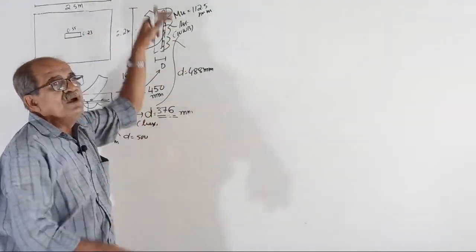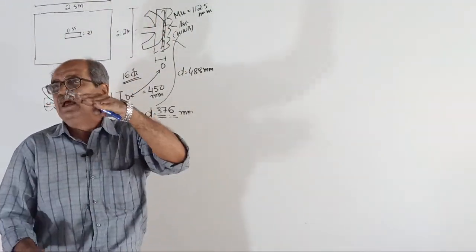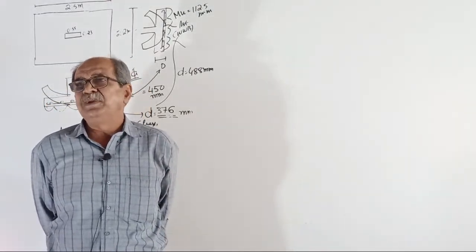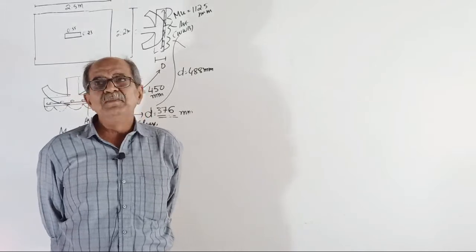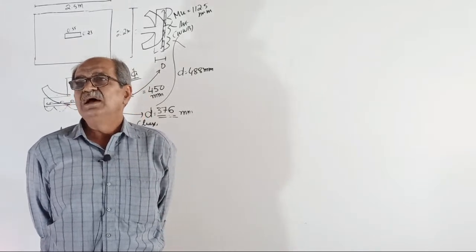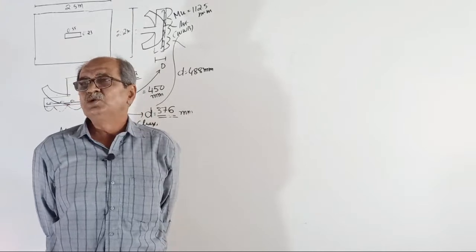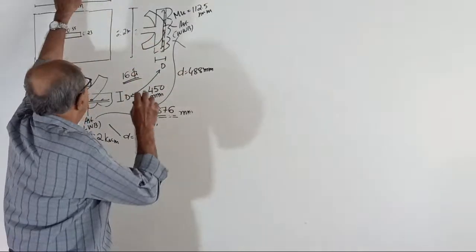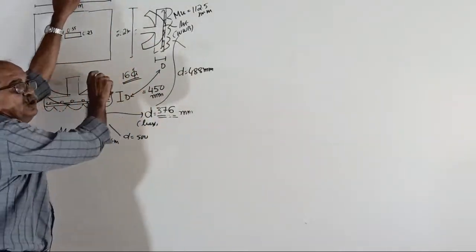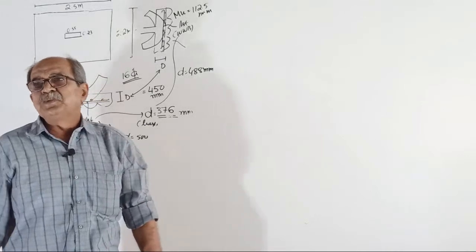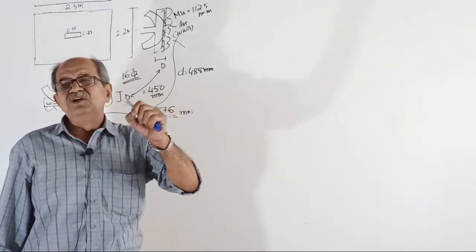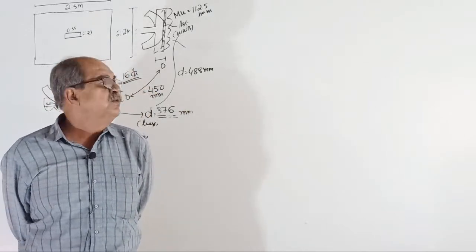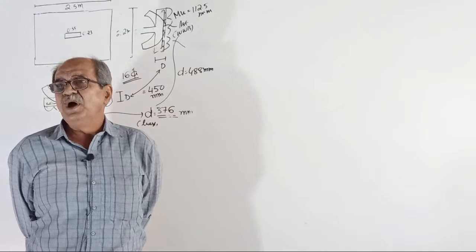Around 450 came, so you took overall depth of 450? No, not 450. It comes lesser. Maybe 275, 280 like that. Then remember, I told you, if you provide the depth of the footing slab based on bending, it will be 100% unsafe, because in the case of a footing slab, shear is very critical.